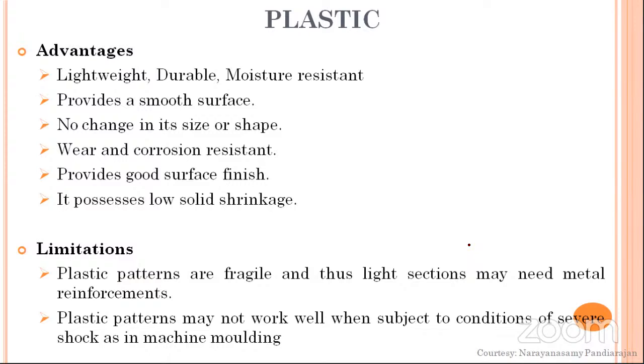The reason we are stressing the smooth surface is that your end component surface finish depends upon the surface finish of your pattern. If the pattern is smooth, the final product will also have a smooth surface finish. If your pattern surface is rough, then obviously your end component surface will also be rough. So depending upon the surface finish requirement of the component, you should also consider it in the selection of a pattern material.